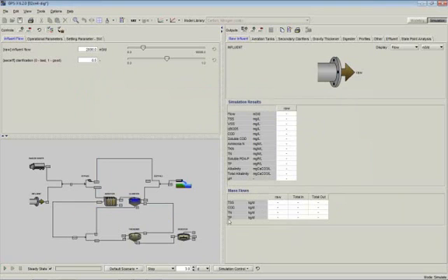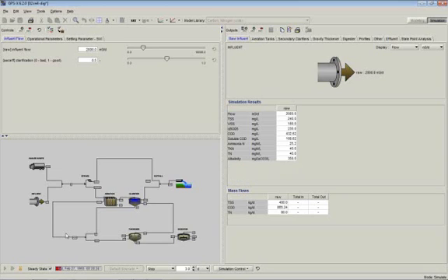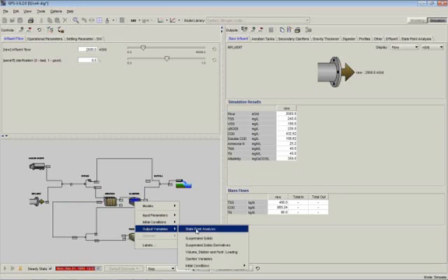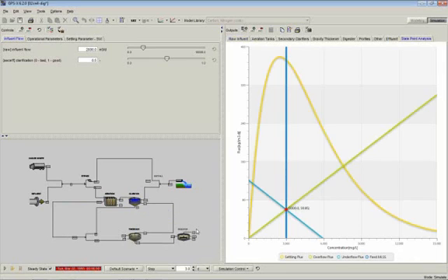So I'll also mention our state point analysis now. So I'm just going to run a typical simulation here, our default scenario, and our long-standing carbon-nitrogen demonstration layout that we've had for many versions of GPSX. And if I go to the clarifier object, right-click, and go to the state point analysis menu item underneath output variables, you'll see our new feature here.